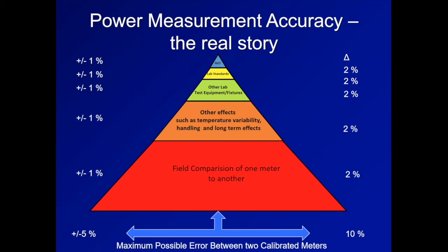And a secondary standard has to get calibrated to something. Well, what do we calibrate it to? We calibrate it to a primary standard, which is NIST. So the calorimeter that you might use or the reference standard that we use is calibrated to a NIST standard. So now when you do that, you have to add yet another 1%, because there's something to keep in mind: in power measurement, 0.05 dB is roughly 1%.